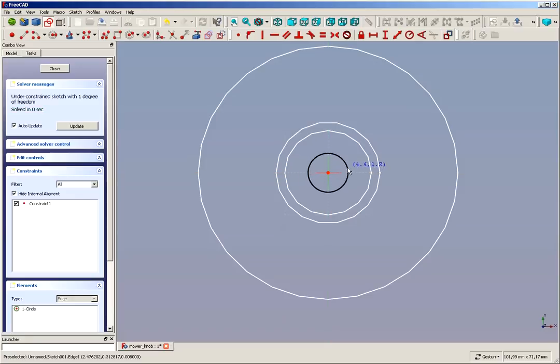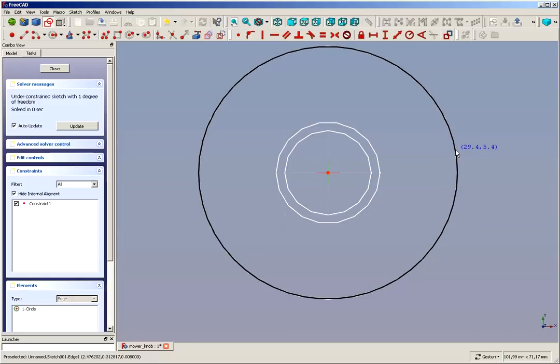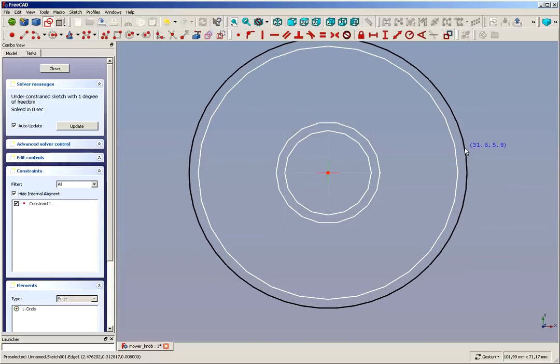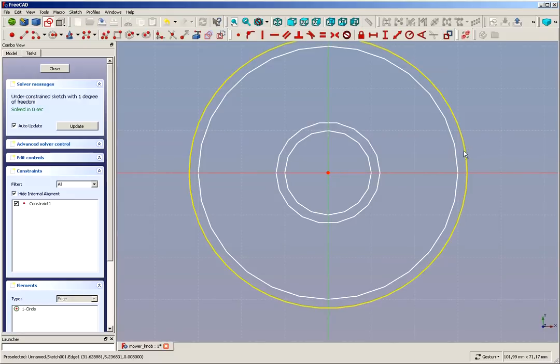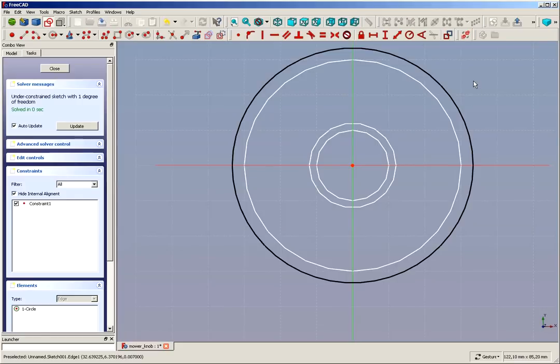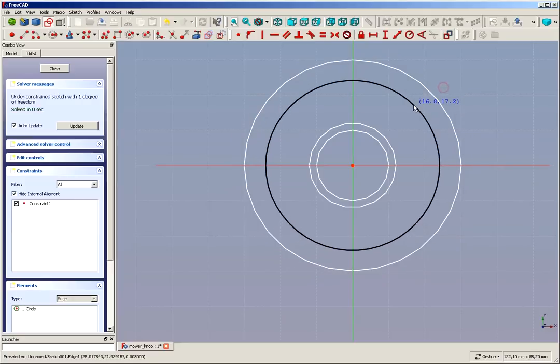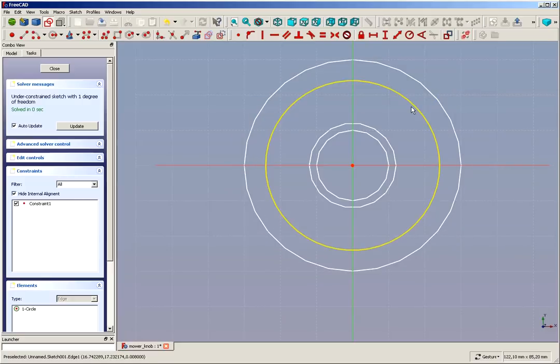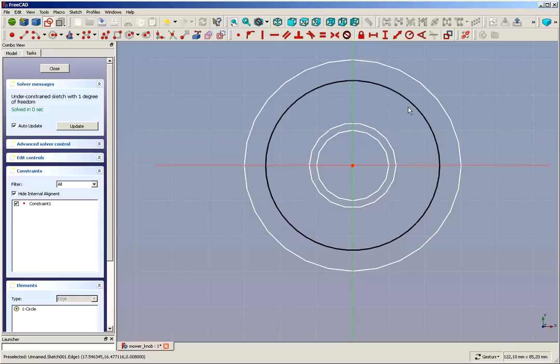When you create circles, don't try to create them so they lie on a different circle that exists somewhere, because then it will try to make the circle tangent to the other circle, which for concentric circles is not going to work. So we better do this by choosing a random diameter first, and then using constraints, getting it to the same diameter.